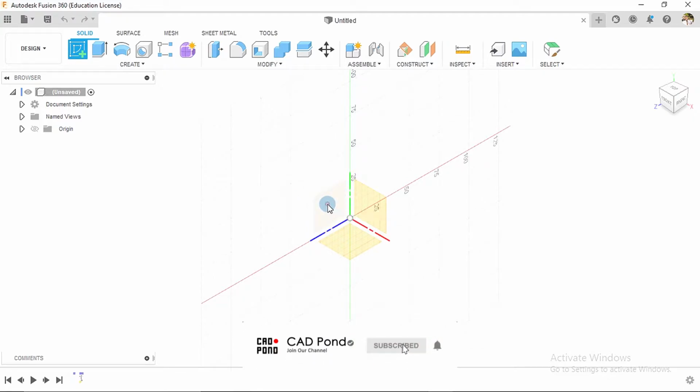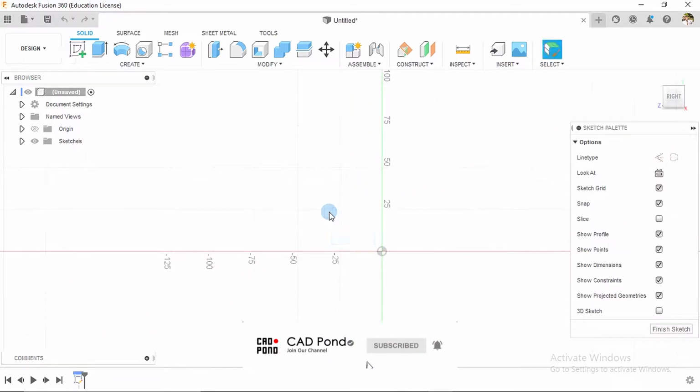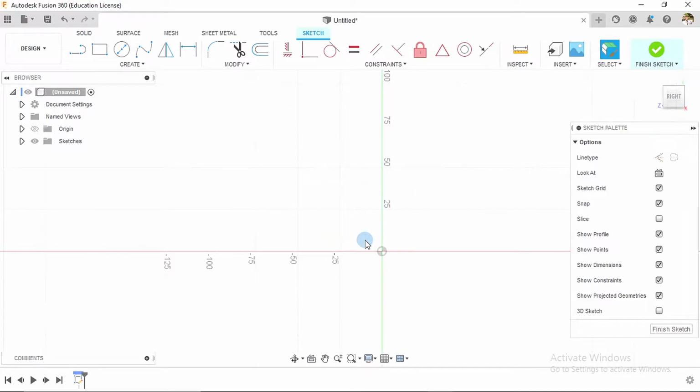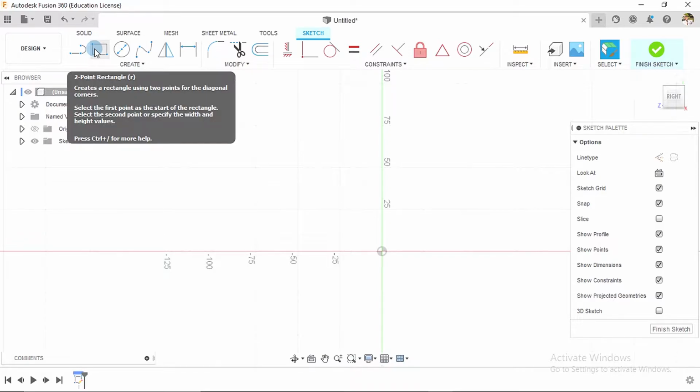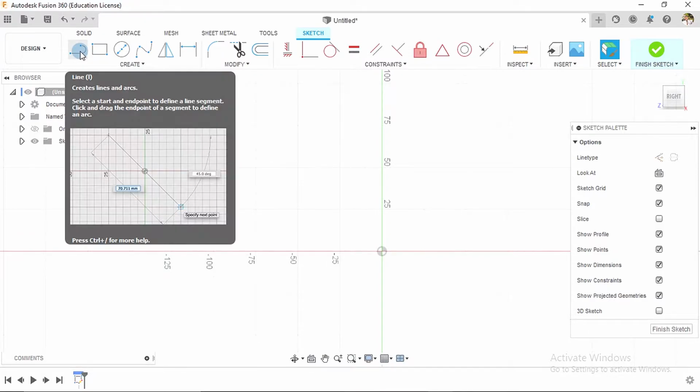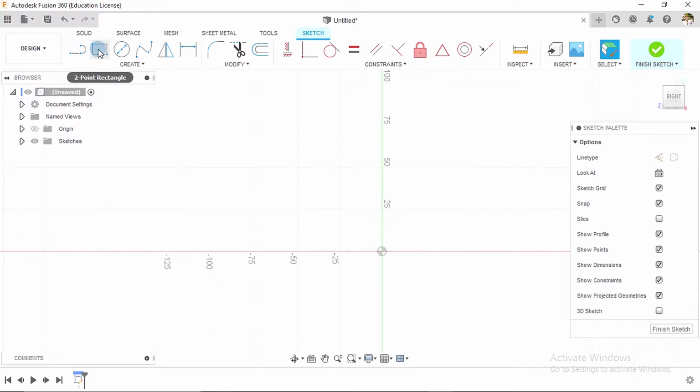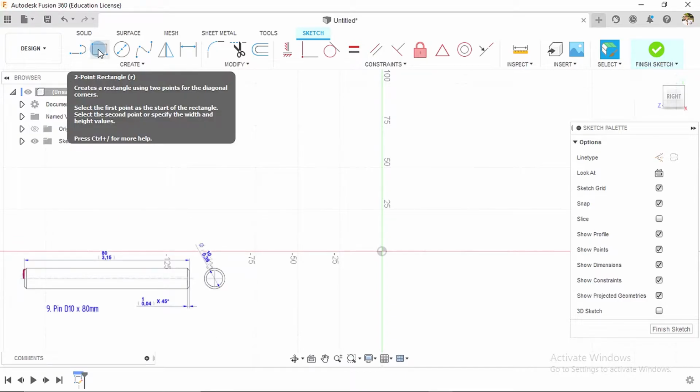All we need to do is go to the front plane or any of the planes. There are several ways to do this. You could just create a circle, extrude, and create a chamfer, but like I usually say, in that case we have three features here. So my weird behavior is that I always try to have as few features as I can imagine.